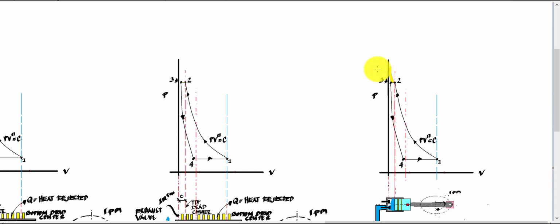But it is a common practice that the operation of the multi-stage compressor is adjusted to have approximately an equal amount of work done in the cylinder. A practice that will result in the minimum work of the compressor given the quantity of the gas.